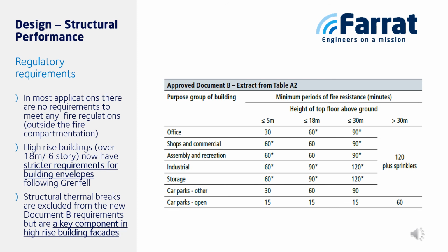Structural thermal breaks, like most building materials, can be produced with different grades of flammability and performance under fire loading. Where fire sits high up on the order of risk, alongside structural thermal performance, choose a certified fire-resistant material. This is a topic that we'll look at in Module 2 of Structural Thermal Breaks.